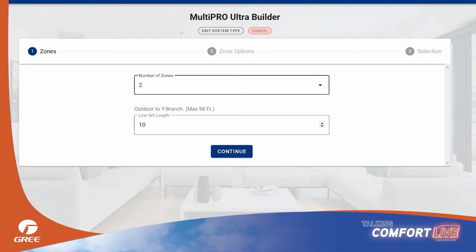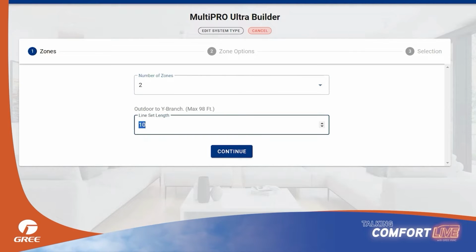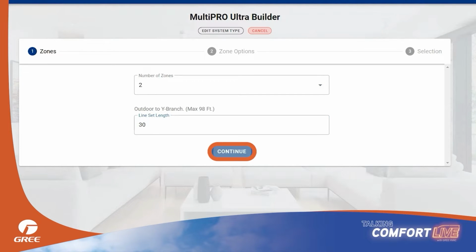Next, there's the line set length. The line set length can be an estimate, but at some point you need to go in and measure the line sets and enter that information accurately so you can get the proper amount of additional refrigerant charge. So in this case, we know that from the outdoor unit to the Y branch, it might be 30 feet. So we simply enter 30 feet and then click Continue.